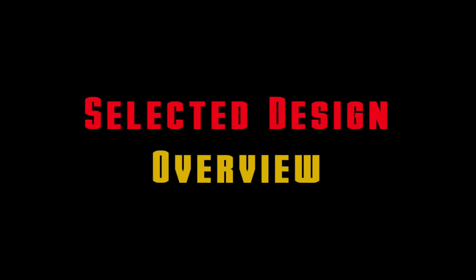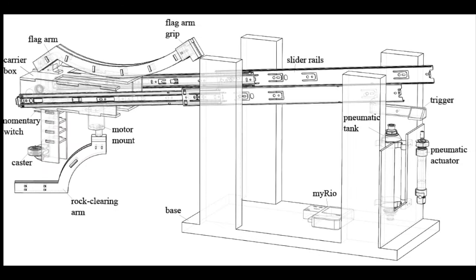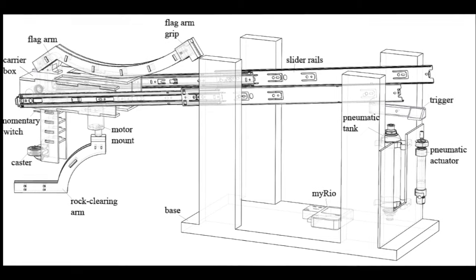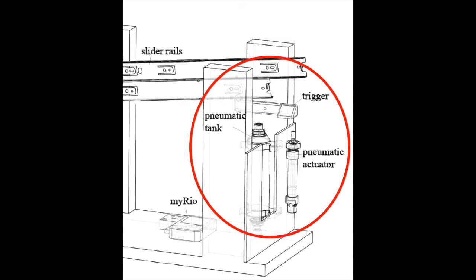After going through the house of quality, specification sheet, function tree, and morphological chart, the following designs were selected to accomplish each of the tasks. For the trigger mechanism, a custom 3D printed part, an actuator, and the gravitational potential were used. The trigger itself is attached to the column with a single screw. A loop is connected to the body of the machine, which is tied around the collar of the trigger.